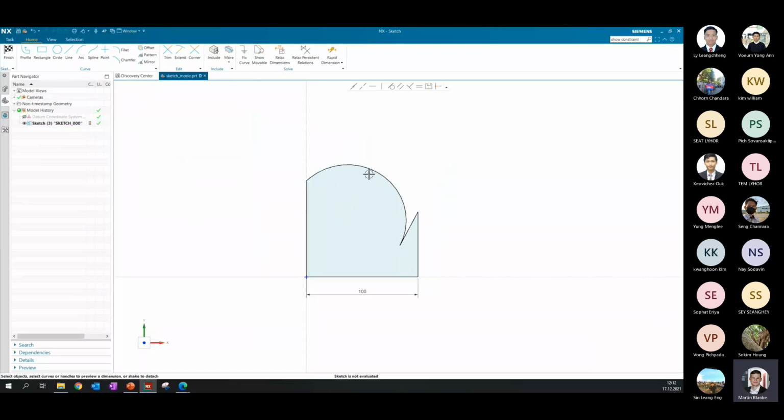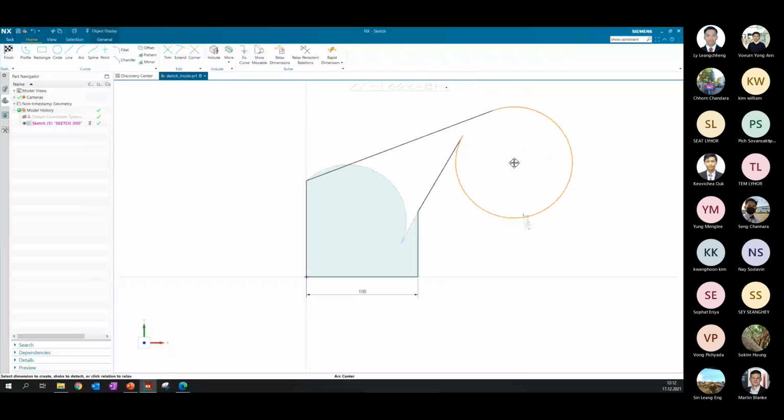It's not really the shape I want to create. So now I have the possibility to move the sketch. So click on this line maybe, and on the center point, and click on your left mouse button, and then I can drag my geometry to the top. I'm not fine with this point.